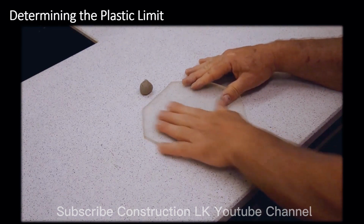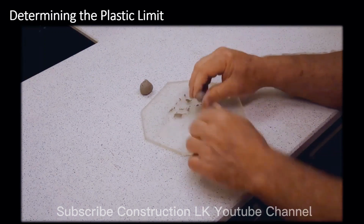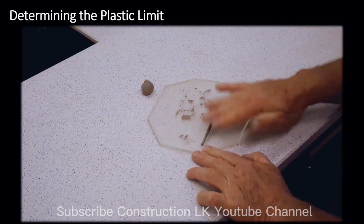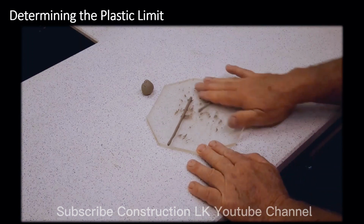This mass shall be rolled between the palms of the hands and the ground glass plate. The mass should be rolled with just sufficient pressure to make it into a thread of uniform diameter of about 3.2 millimeters. A rod may be used to get guidance about the size. Any crumbling of the thread should be observed during the rolling.